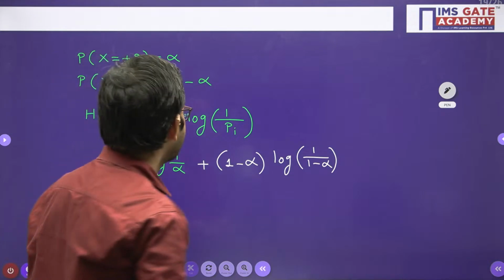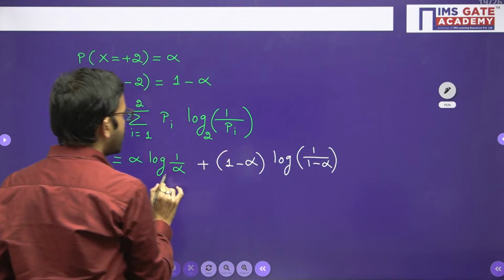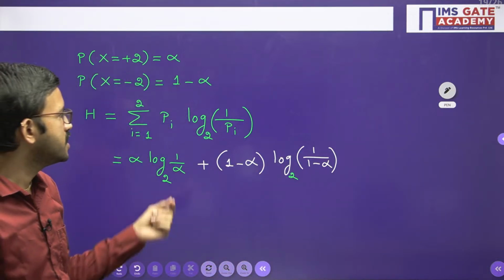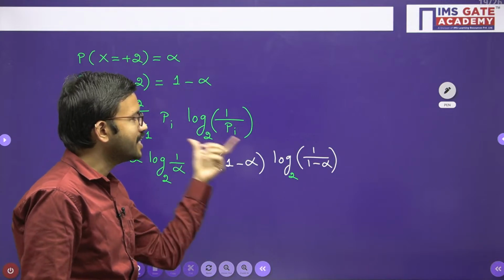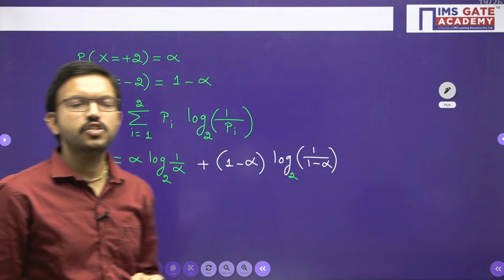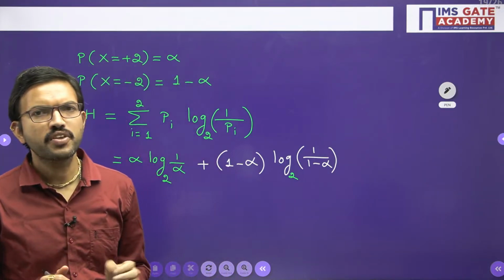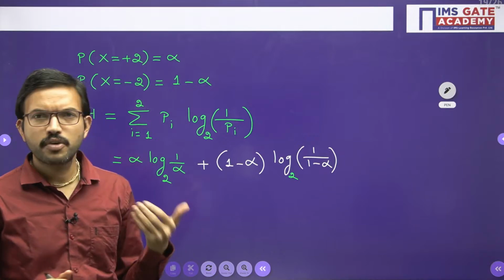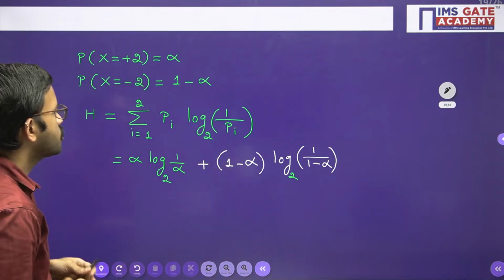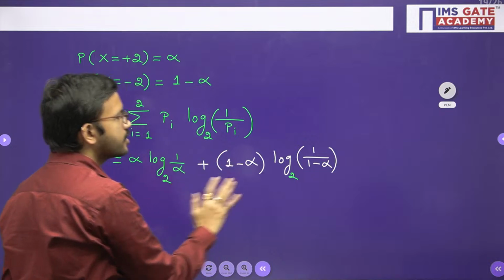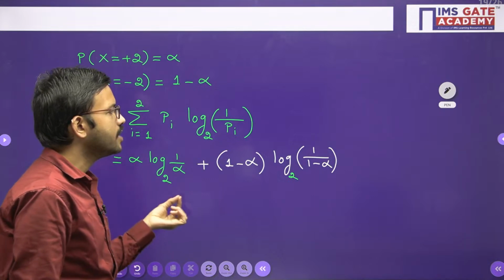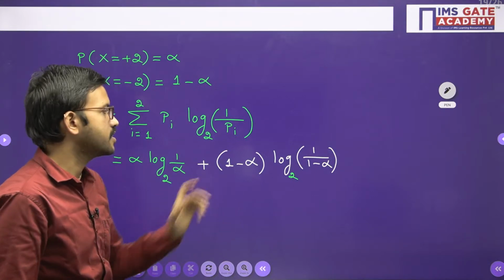Yes, very good Manoj. This is a concept we are studying in information theory. In information theory, the logarithm base value is 2. For the generalized case it can be b, but since we are dealing with binary values, the base value is 2. Whenever you are doing calculations regarding signal to noise ratio, voltage gain, current gain or power gain, logarithms are used there, so you have to be very careful about which base you are considering. Whenever the base value is 10, you need not represent it, but whenever the base value is 2 or e, you can represent it.